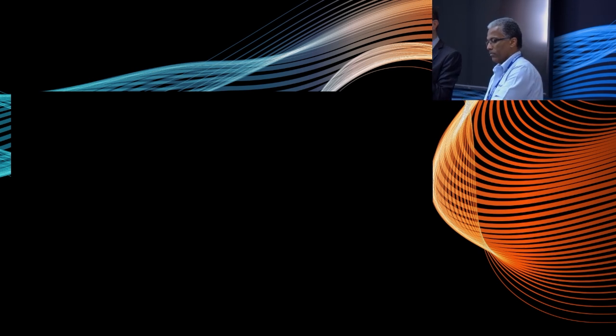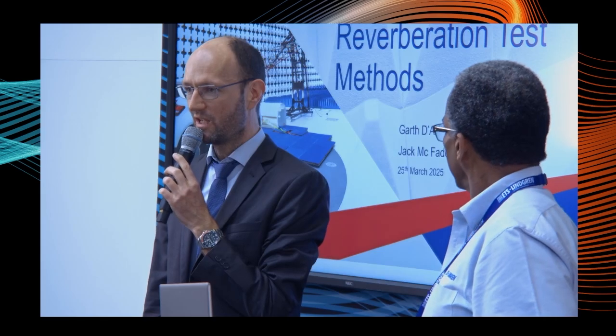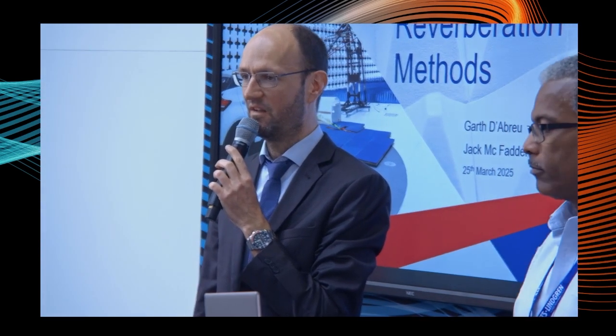Can you combine the two techniques and try to find some balance where you get the best of all worlds? Yes and no. So I would say the existence of reverberation chambers is not really the end of anechoic chambers, because reverb chambers always have a problem going to low frequencies. If you want to do emission measurements or immunity tests starting from 30 megahertz, it's very, very challenging to build a reverberation chamber for this frequency because it would be very huge.